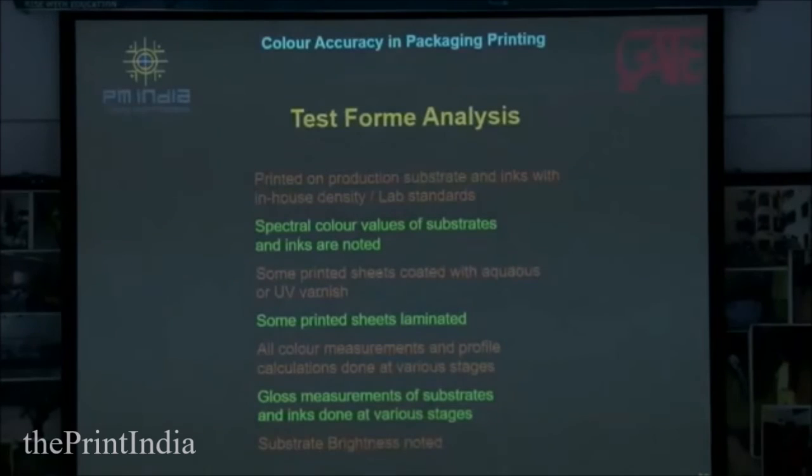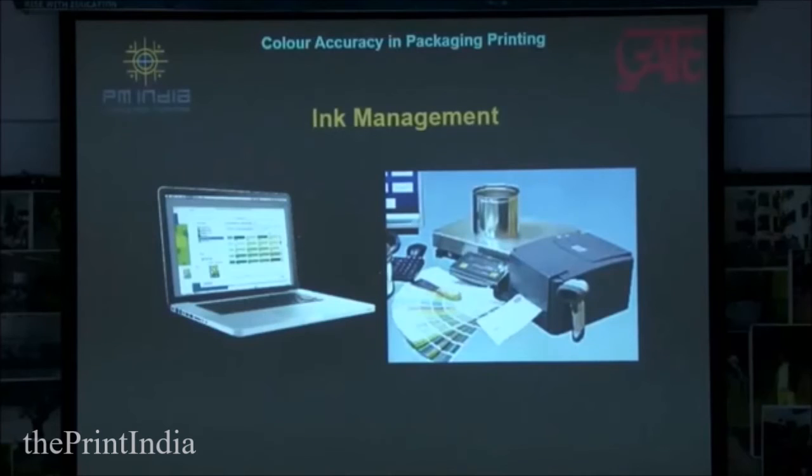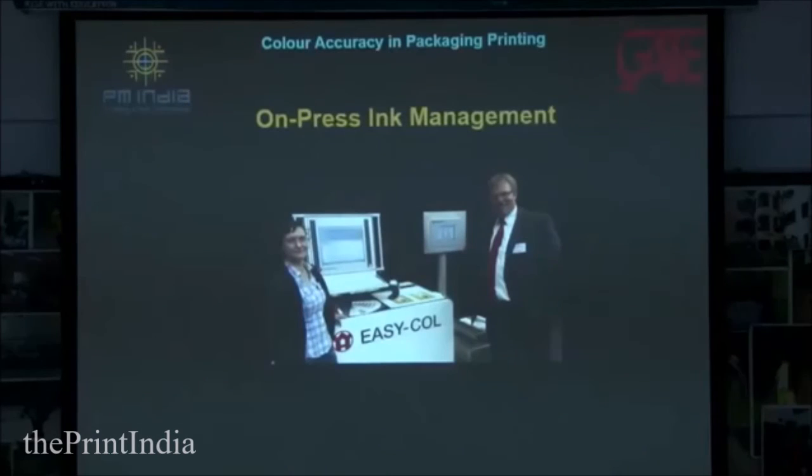Gloss measurement of the substrate and ink is also done at various stages, and the substrate brightness is noted, how bright, okay? Because some pastel colors will look good only on bright papers. If the paper is not bright, the pastel will not look bright, it will look dirty. So ink management is very important.